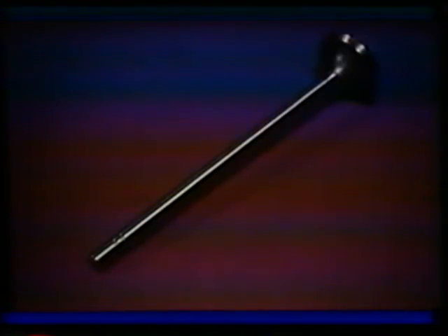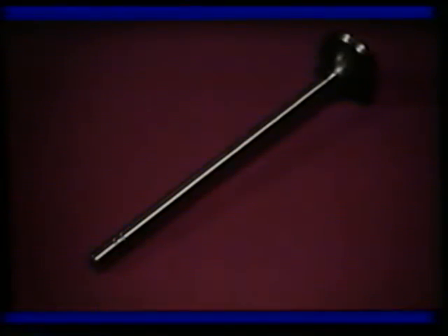It must be able to withstand the heat and pressure which is generated during combustion without warping, cracking, or distorting. The stem is subject to wear from friction with the mating valve guide, while the face of the valve will wear against the valve seat. Wear resistance is also important at the tip, as it is peened millions of times by the rocker arms. In fact, on a 3208 at 2800 RPM, the valve tip is peened by the rocker arms about 84,000 times in 1 hour of operation.